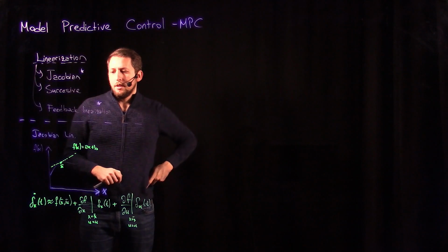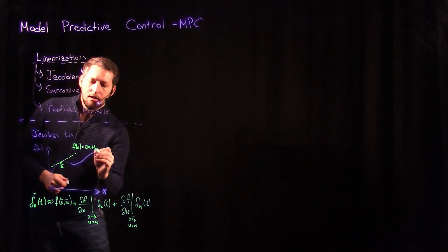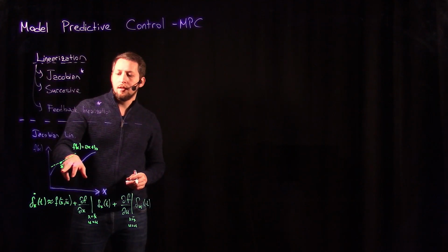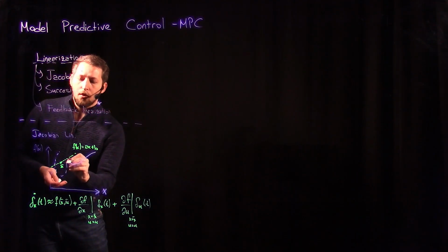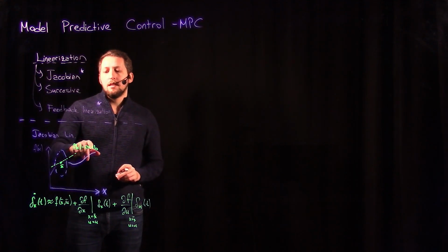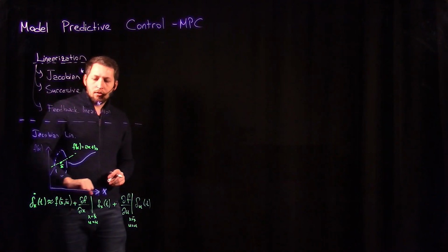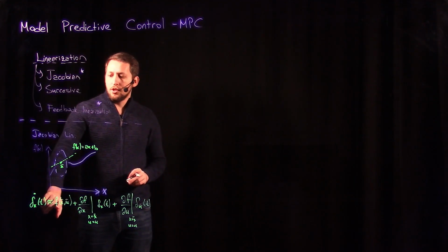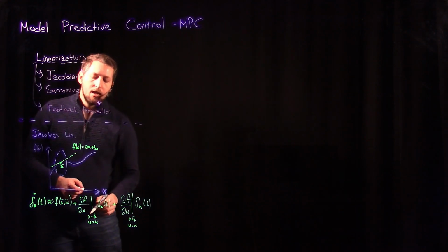So, in the case of Jacobian linearization, informally speaking, what we are aiming to create is, for example, let's assume that we have an original f(x) signal, something like that, and we have an operating point or equilibrium point that shows itself in the form of x dash. And our intention is to linearize the system around this working point. And as you can see, since this is a basic example, the f(x) can be directly linearized as Ax plus B. So this is what is intended to be done. And in order to realize that, we need an additional variable here, and we need to take the Taylor series expansion of our original system f(x) and evaluate it on the equilibrium points x and u.